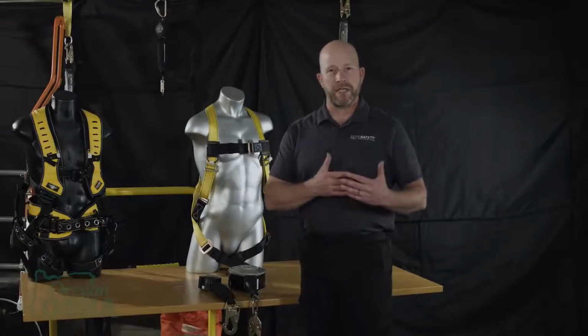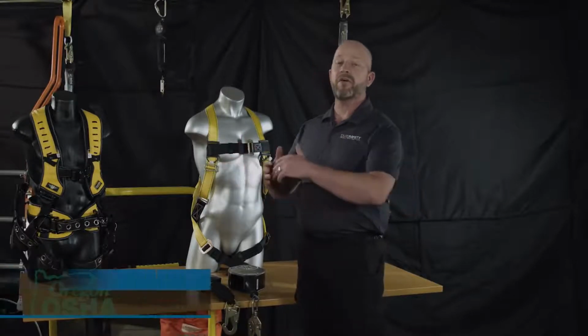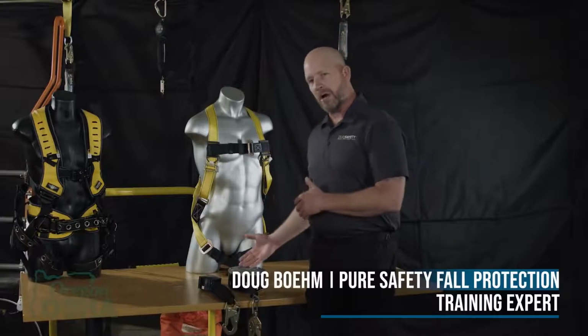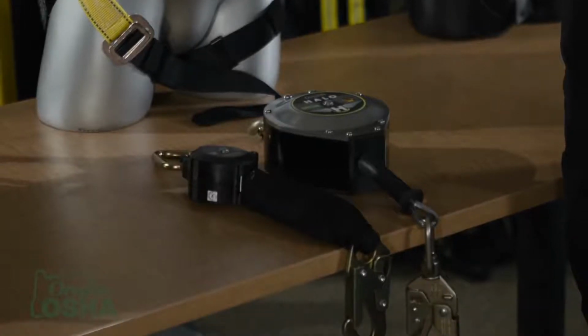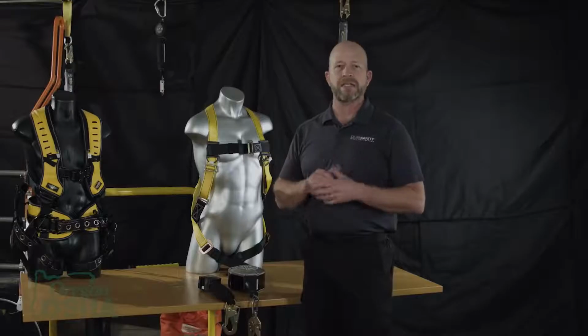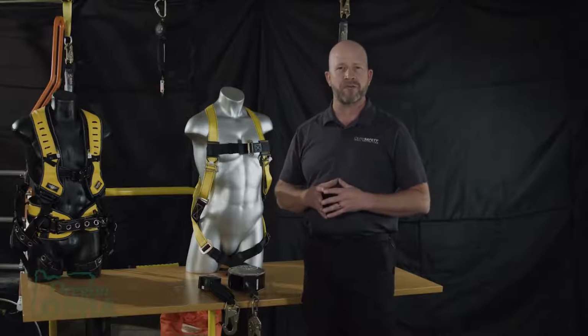The benefit to using an SRL versus using a lanyard is that on a lanyard system, although it is a fixed length, you have to fall the full length of it before deceleration occurs. Whereas using a retractable, it has the ability to arrest the fall in a very short distance. Class A's are 24 inches or less, Class B's a maximum of 54 inches.